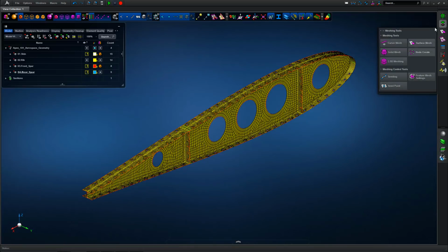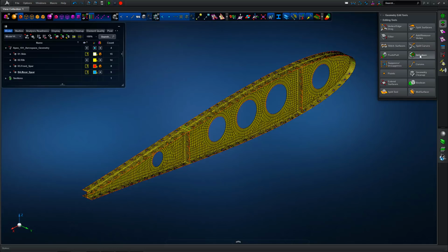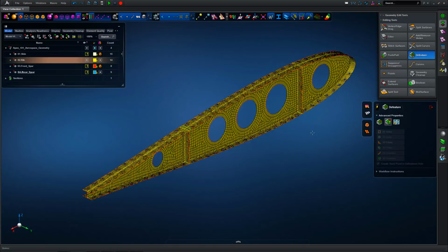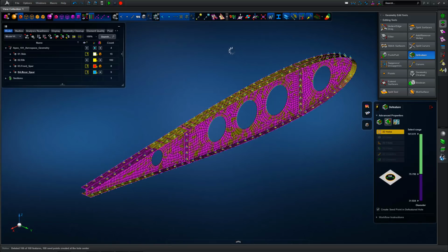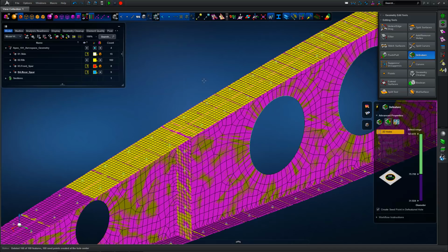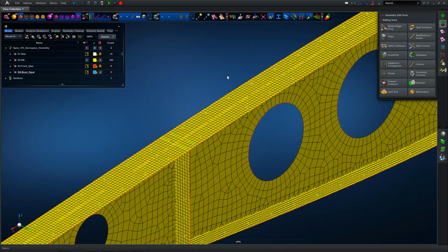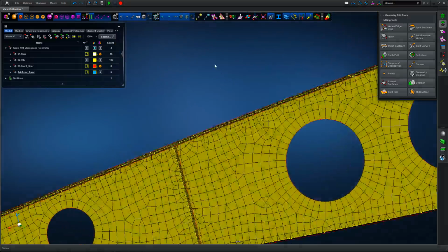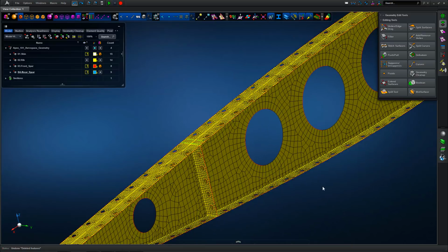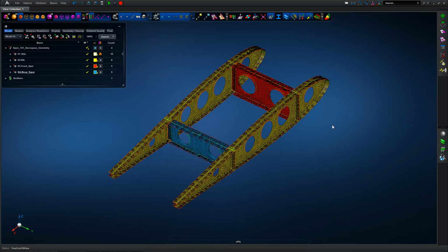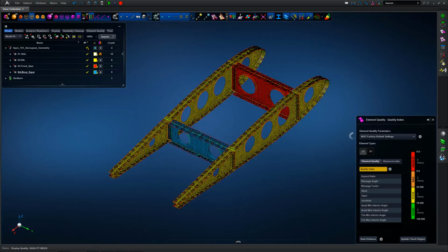We're now going to defeature again. Similar to the rear subspar that we just looked at, but picking out the fastener holes and defeaturing on the fly, creating seed points at hole centers, and the geometry is updated with the mesh very quickly. And again, we can use this definition for a node-to-node fastener representation if we so desired. But in this case, we're using the hole-to-hole approach, so we're going to undo that defeaturing step to allow us to return to the original definition.